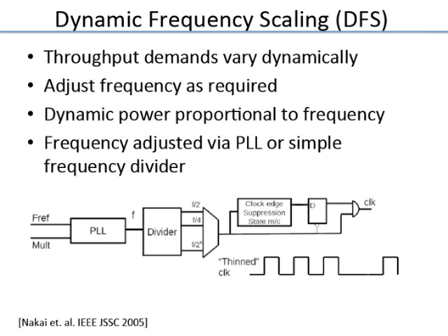And how do you adjust this frequency? Typically in any of these chips you will have a clock source, a reference clock coming in. There's something called a PLL, phase lock loop. The reference clock will be a few megahertz, and the phase lock loop will multiply it and generate an internal clock running at whatever frequency you want, a few gigahertz. And that multiplication factor you can change if you want.